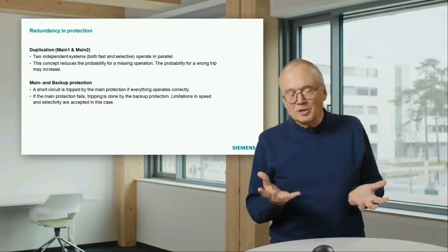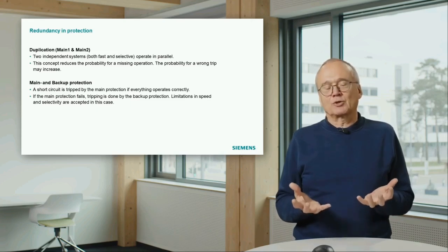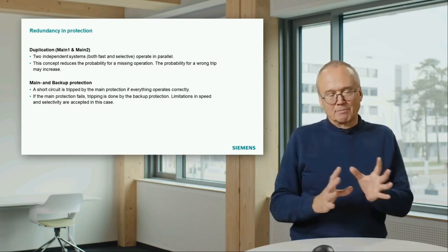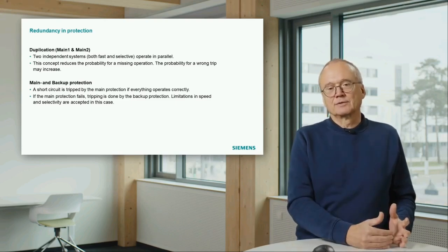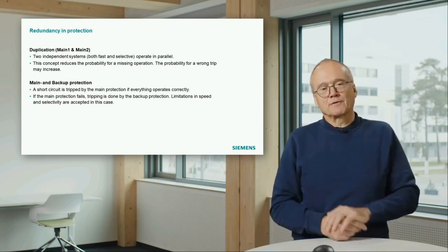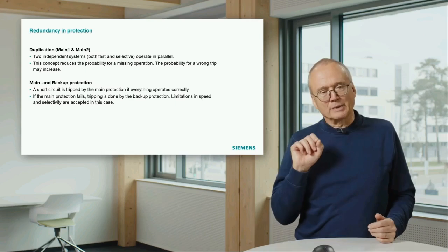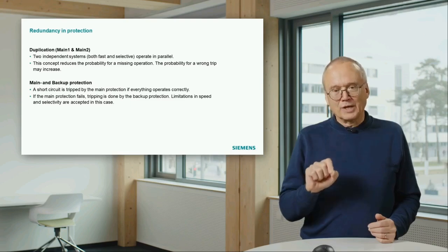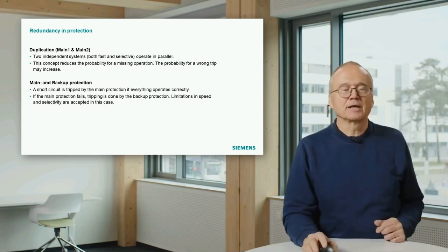And also here you can again see that it is the economic constraints. Economic constraints bring you in a situation that you accept additional risk. Well, you have reduced selectivity, longer tripping times to save some money. But it's state of the art to do that. An important rule behind that, in all cases you must think about which device does the backup in case of a missing operation. That's always the idea behind that.